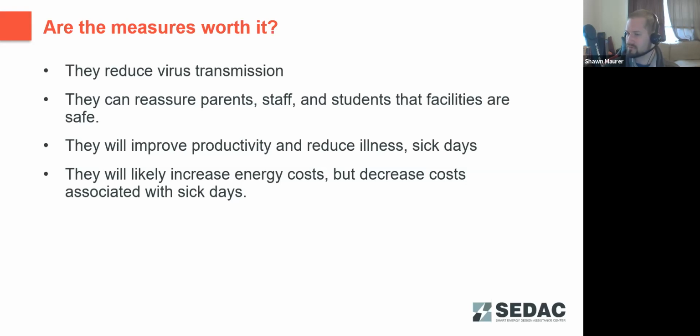But I do know some air purifiers, particularly if you're doing an in-room fan unit with a filtration system, will create some additional sound level in the room. There are units that are specified for lower sound decibel ratings that are more applicable to school facilities. But I do want to caution against silent units, ones that are fanless. Again, they don't circulate air through them very well, and so that reduces the clean air delivery rate.